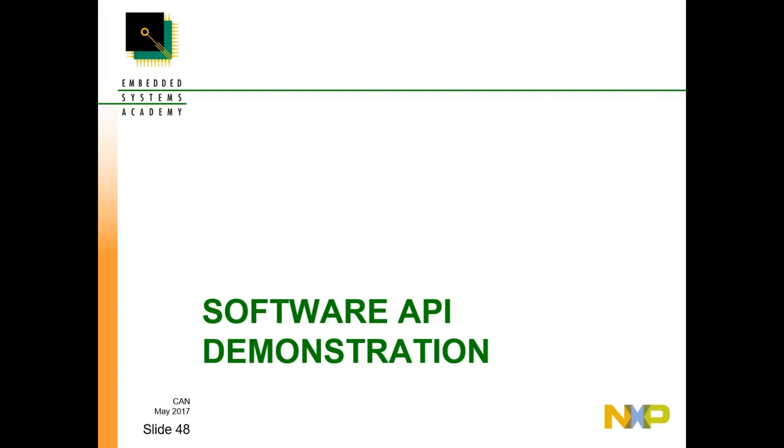I'll now give a short demonstration of using the API. This demonstration doesn't cover all functionality, as some of it is mutually exclusive, but it will demonstrate configuration, transmitting and receiving. For the demonstration, I will switch over to the MCUXpresso IDE. In conjunction with this, I'm using an application called PCAN-View. This is a free utility. It comes with all PCAN interfaces and allows straightforward, simple transmitting and receiving of messages.